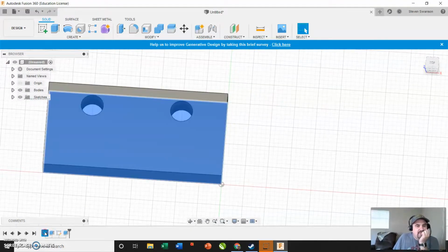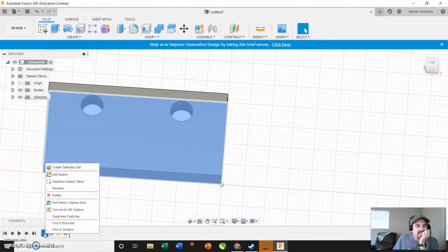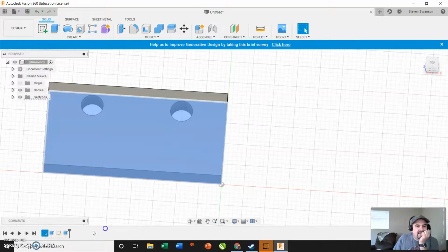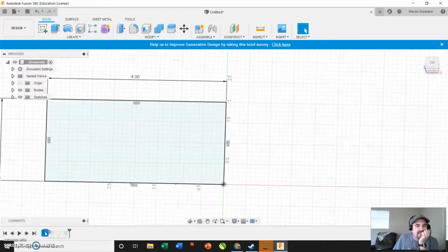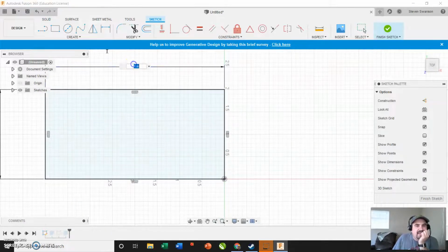I'm going to go to the first sketch right here. This is how you find them on Fusion. You go over here and this is your history. That's my first sketch. Then I extruded. Then I drew again the circles. Then I extruded. You see the 4 things? So I'm just going to right click here and you can say edit sketch. I think you could just always double click that as well. Yeah, you can. So I'm going to change this to 8 inches, okay?